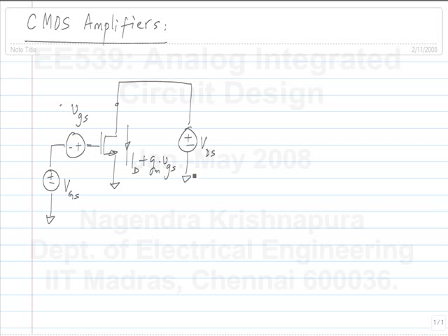We can try to pass the current through a resistor. So, this is a certain resistance RD. If we want to make sure that the operating point was the same as before, what do we need to do? In the quiescent condition, you get a drop IDRD, and across the drain and source I want VDS. So, this should be a larger value. So, the larger the value of RD, the larger this voltage needs to be. So, what will be the voltage across RD? When you apply the input increment, what happens to the voltage across RD? If it is defined in this direction, it is plus.